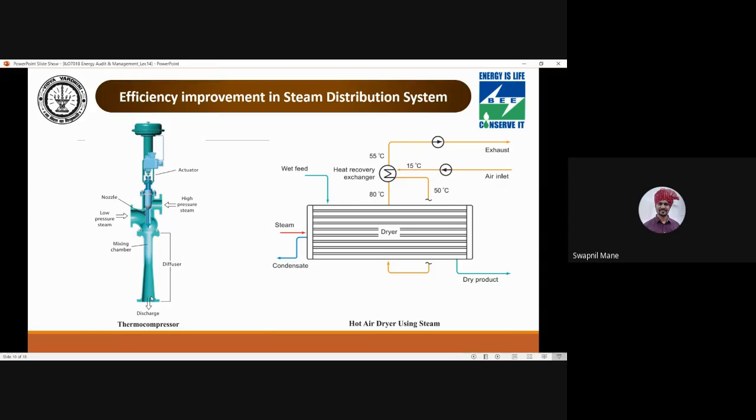Okay, so drying is a process by which a liquid, or we can say water, is removed from the material. This is usually achieved by applying heat, typically steam or a carrier gas through or over the surface of the material. The objective of drying is to form a product that meets the water content specification. So the amount of water removed depends upon the desired product. Okay, the basic drying energy requirement is the latent heat needed to evaporate the water. Clearly, this depends upon the amount of water being evaporated.